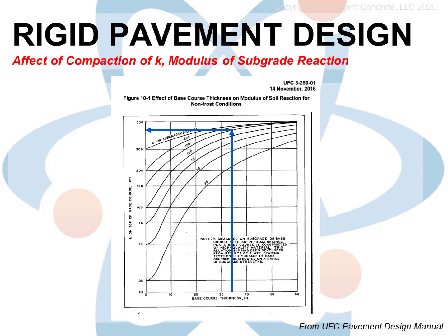Other measures like adding synthetic reinforcing blankets between layers of compacted soil or making a base layer of heavy rock followed by several feet of compacted good quality soil can also be used. Remember, this class is a 30,000-foot view of rigid pavement design, so we won't be getting into the art and science of soil modifications for pavements. Just know that for every problem we might encounter in designing pavements, we probably have a solution. Many of them learned the hard way, such as the DFW runways and taxiways.